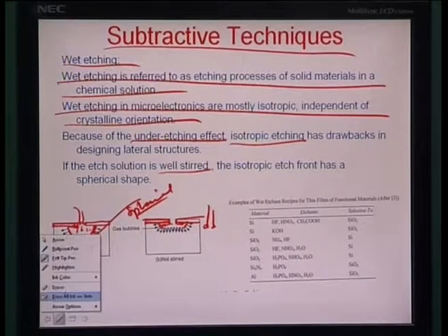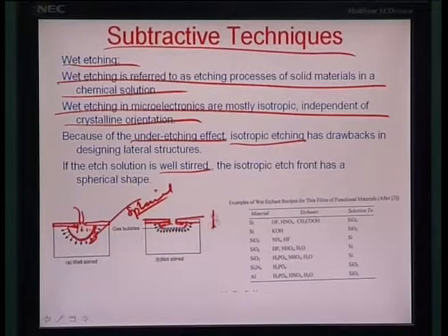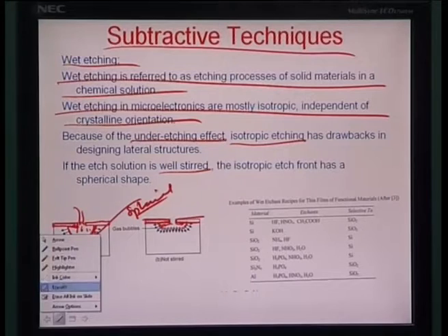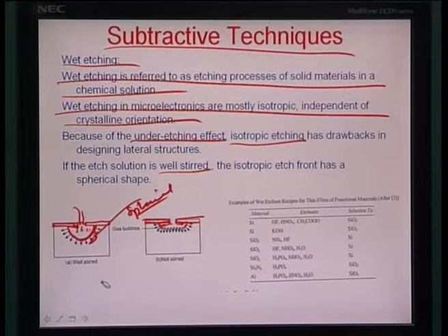Okay. So, essentially you can consider that more area is being exposed to the etch process in the bottom, due to which there is more amount of material dissolved from the bottom. Okay. And there is a concentration gradient which is created, as opposed to the sides probably where very less amount of material is withdrawn from, and that is because of the low etch rate in the linear direction.